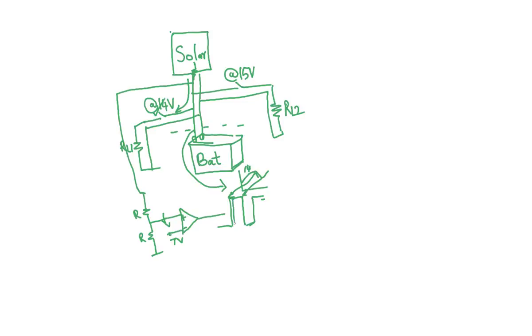So you'll actually get something like that, going up and down, going up and down. So this is a terrible thing to do, right? Both through your load as well as the solar panel and your battery, you're continuously connecting and disconnecting a load. And this voltage will also look actually the same. I had drawn it just to demonstrate what happens. It will keep going up and down, and that will be the current that you're getting there, and the output also will look the same.